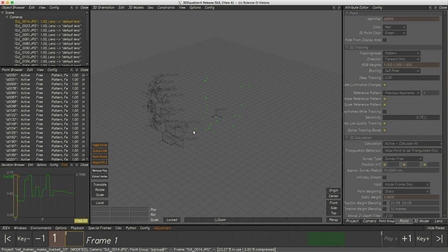Okay, there's now a reconstructed scene with cameras and 3D points, but for a good reconstruction of the castle, still too few ones. Of course, we could have started with more active points per frame in the first place, but as always, that would have cost us a lot of performance. A different approach is simply using the now existing 3D camera data to track more points much quicker than before. By using 3D data for tracking, the reference frame auto tracker is able to reduce the area used for finding set patterns in other cameras, which is way much faster than without this information.